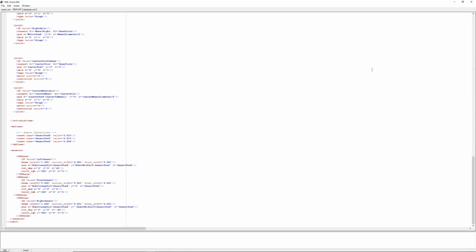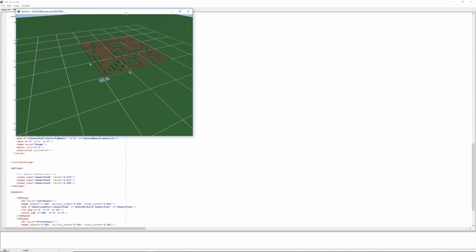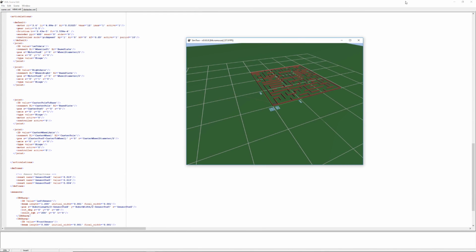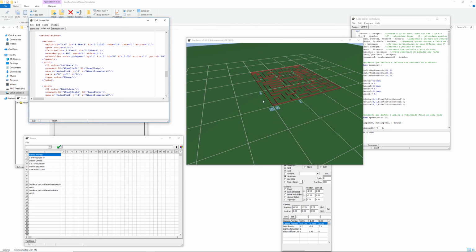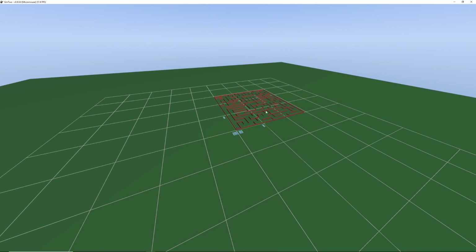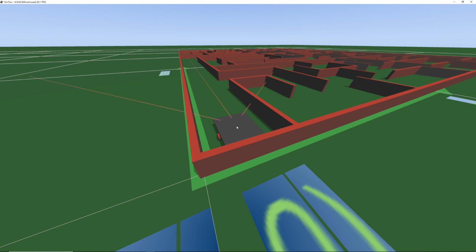To bring our robot to the initial position again, we go to Scene and hit Rebuild, Ctrl B. Now this puts our robot back to the home position at the 0 position right here. So you can see that our robot is now not moving and is in the home position.